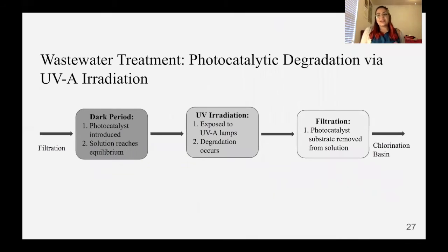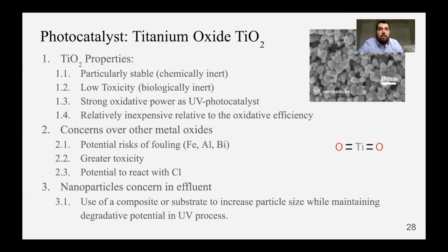Our wastewater treatment, in terms of the design, is going to come in 3 steps: the introduction of the photocatalyst, then the degradation with the UV light, and then a final filtration step. The photocatalyst we decided on was titanium oxide, or titanium dioxide, because titanium oxide is the most commonly used photocatalyst because it is particularly stable, has low bioavailability, and strong oxidative power as a UV photocatalyst. Additionally, it is strong as an oxidation agent relative to its cost, thus it has a high value.